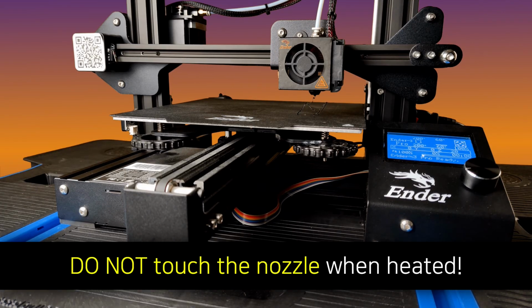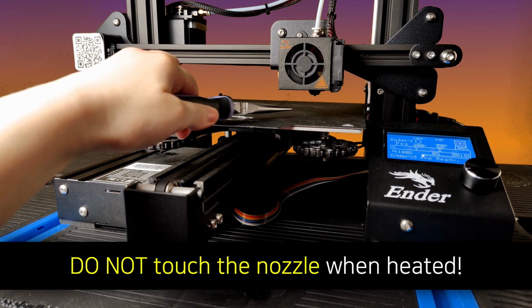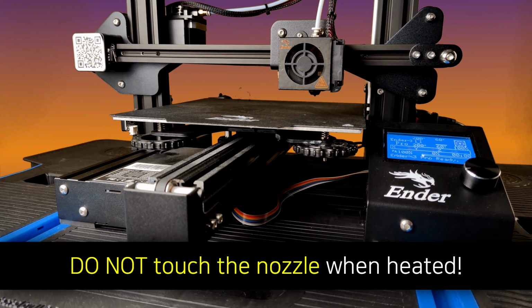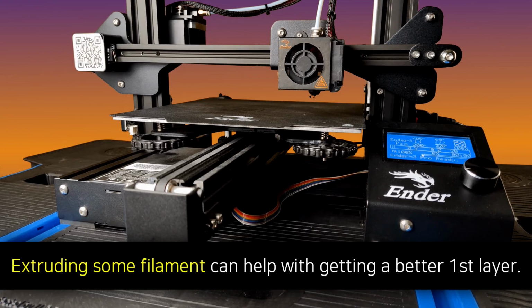With that being said, do not touch the nozzle, it is very hot. I like to use a pair of pliers to grab the filament once it's done oozing out so that my hand isn't anywhere near the nozzle. Once the printer is done preheating, I then extrude 10 millimeters of filament to ensure that the filament is flowing and to also get a better first few layers for the print. Again, I am using pliers to grab the filament that's been extruded.